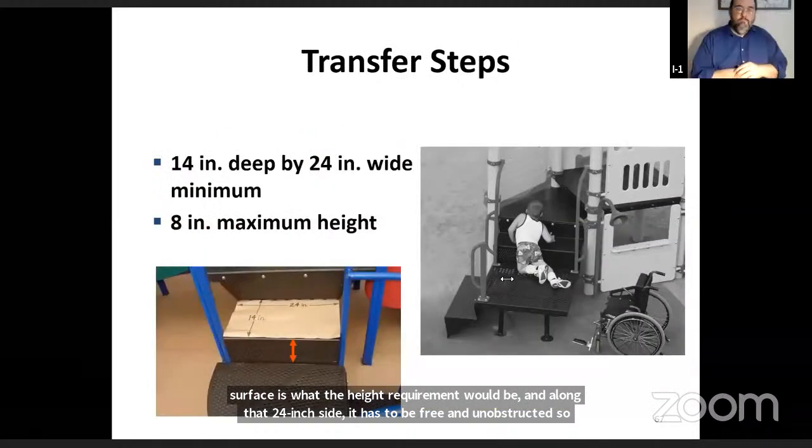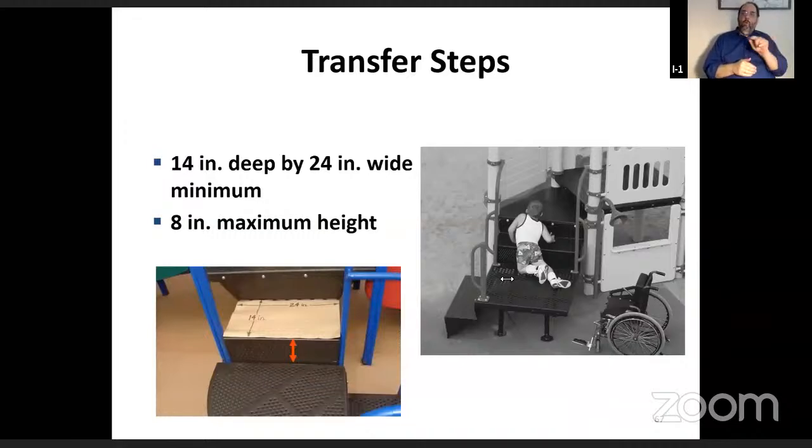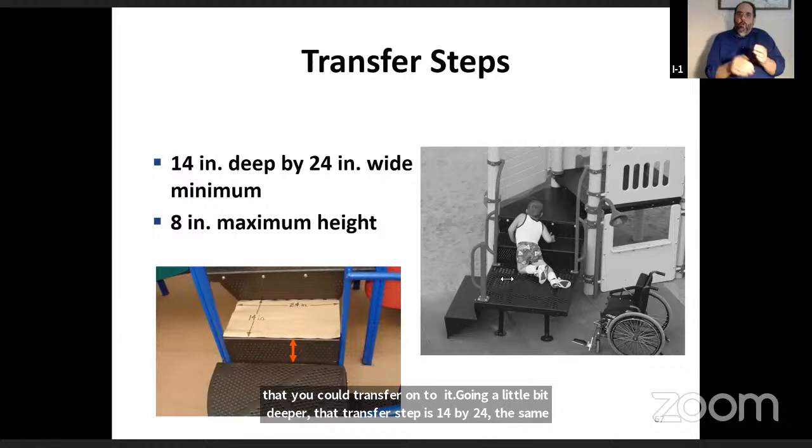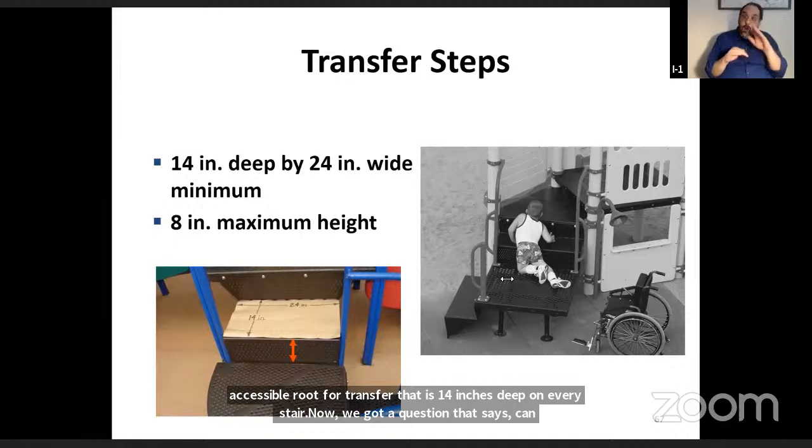Going a little bit deeper, that transfer step is 14 by 24, the same minimum size as the transfer platform. I think a little bigger is always better, but you have a 24-inch minimum accessible route for transfer that is 14 inches deep on every stair. Now, we got a question that says, can my transfer steps be deeper than 14? Yes, they can. Those are minimums.